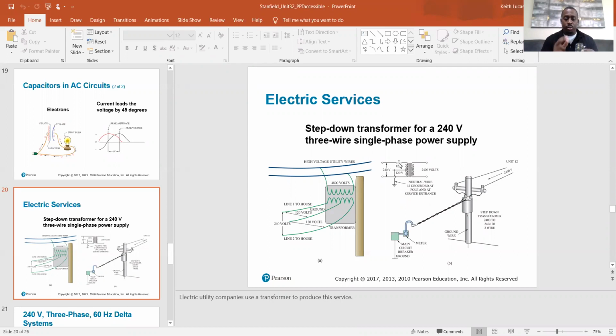So there's two. There's your primary voltage or your operating voltage, which is going to be here and here, but then there's also your control voltage, which is here on the coil, because you need 240 to bring your compressor on. That 240 is right here just waiting to go, coming from your breaker panel. Just sitting here waiting to go.